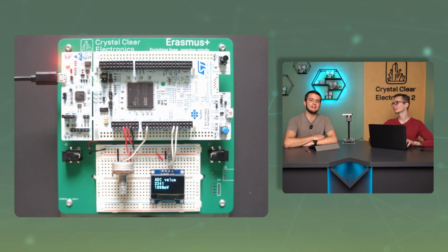Well, I think that if we've come this far, the last thing we should do is to make a program that does a bit more sophisticated averaging than the previous solution. Let's calculate a moving average. This means that our current result will always be the average of the last measured value and the specified number of measured values before it. In our example, this average is calculated from 25 consecutive converted values.